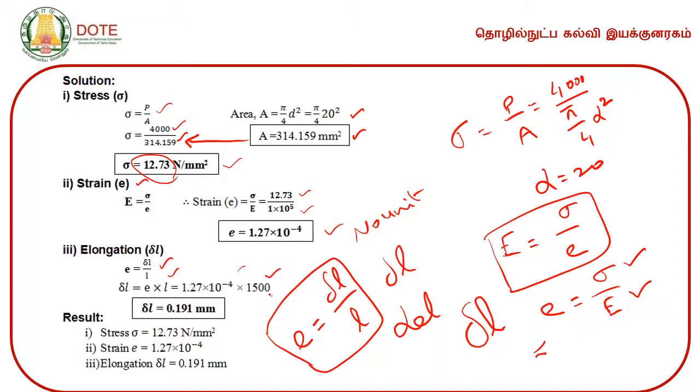Length is given in the problem itself. The length is given as 1.5 meter. This is going to be 1500 mm. So by multiplying these two values, we will get the elongation. Del L is equal to 0.191 mm. So the result is going to be stress sigma is equal to 12.73 Newton per mm square. Strain is equal to 1.27 into 10 to the power minus 4, no unit. Elongation del L is equal to 0.191 mm.